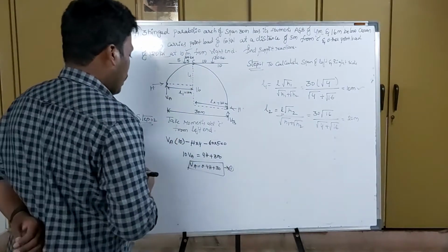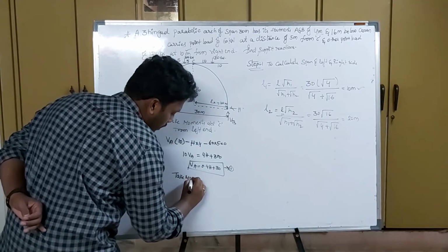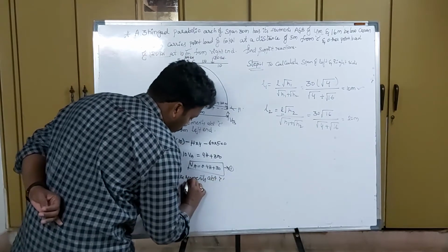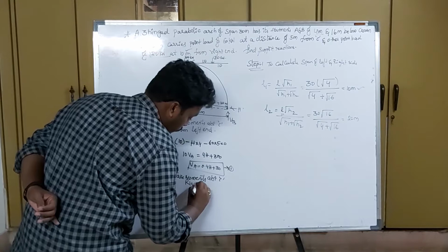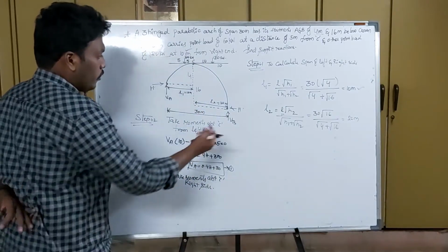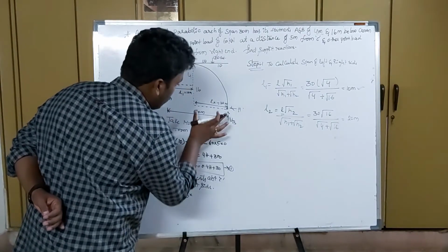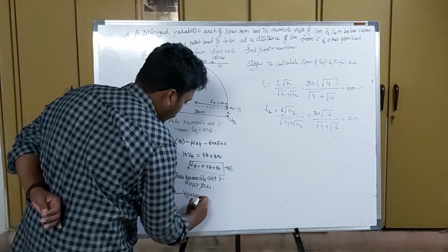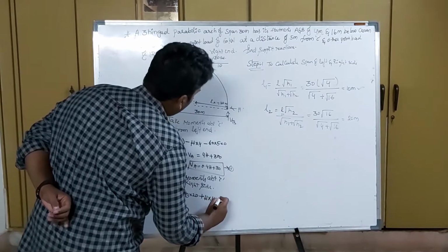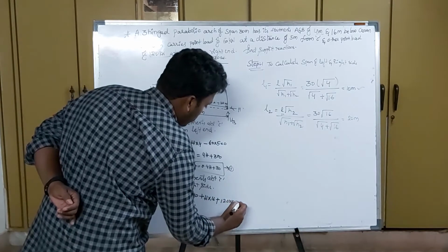So substituting to the right side, take moments about C in the right side. Right side of the section calculation. Going from this side, minus VB into the span from here to here is 20 plus H into 16 plus 120 into 10 which is equal to 0.